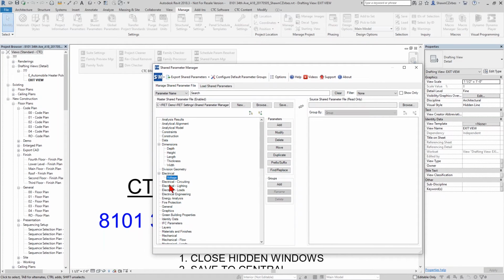If you start making changes here, every single family and schedule and tag that you've already made based on the old parameter definition, you will have to go through that content and fix it because it's no longer compatible with the new shared parameter. So all new content built off this new shared parameter will not work with your old schedules and your old tags, and your old content won't work with your new schedules and new content and new tags that you make based on this new parameter, right? So they're incompatible. They're two different things.